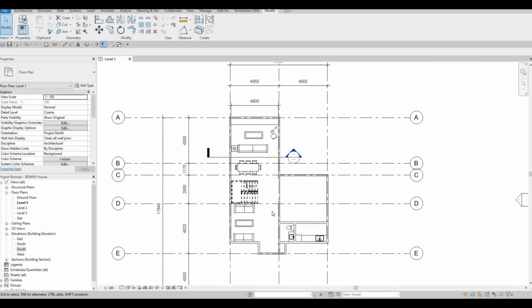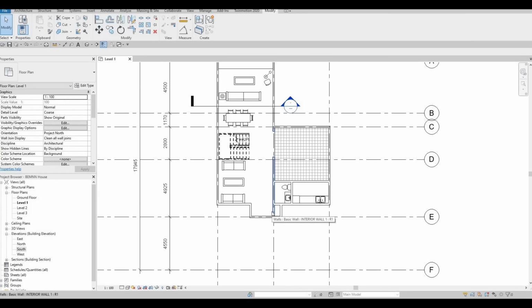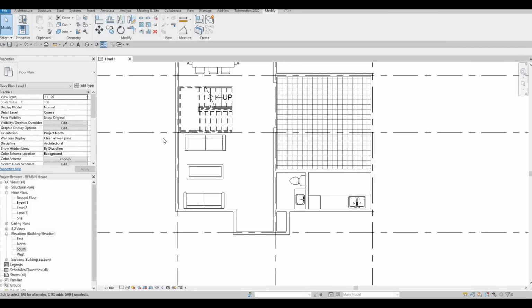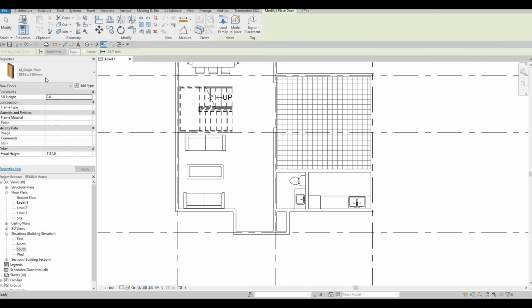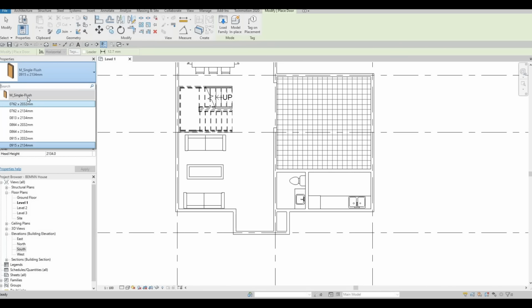And then now, what I want to focus is adding the doors. So I want to go to architecture, and then, or go to insert. Because if we click the door right now, which is DR, short form, we have the basic door that we have here. But this door doesn't have the knob or the leveler for the doorknobs. So that's why I don't like adding this. And plus it looks very simple.